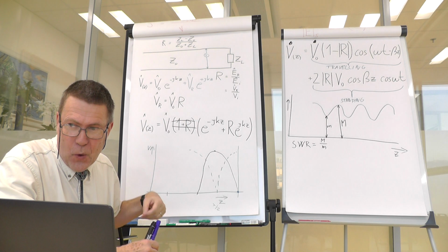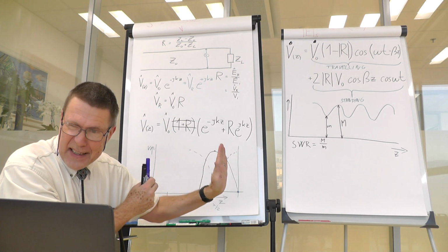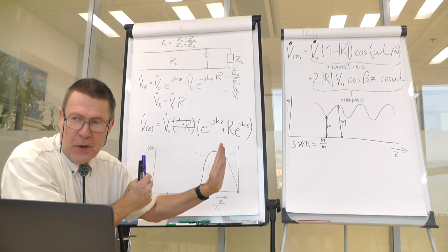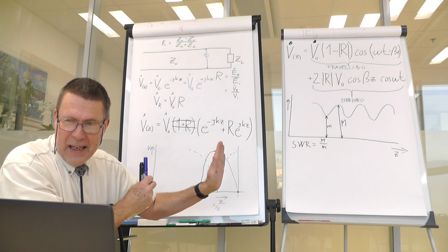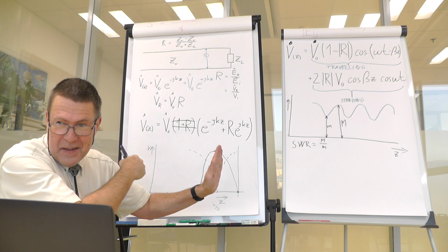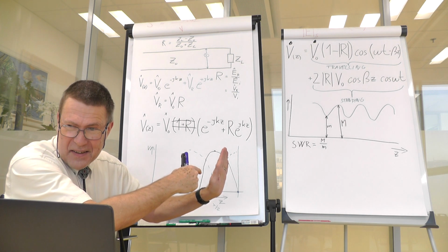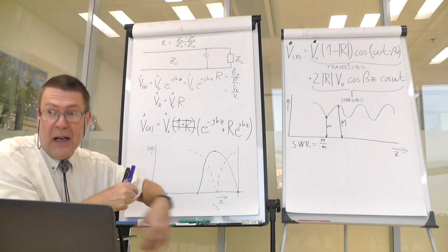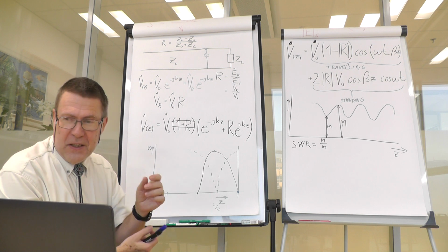So for example, if you have an antenna instead of a generator, and a transistor in the first stage of the amplifier, if you do not have good impedance conditions, the wave travels from the antenna to the transistor, but it does not get in the transistor, so it's not amplified, it just reflects from the input of the transistor and returns back to the antenna and gets radiated somewhere. So this is the first problem.